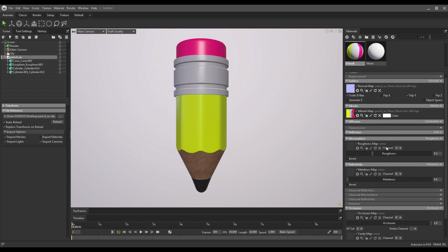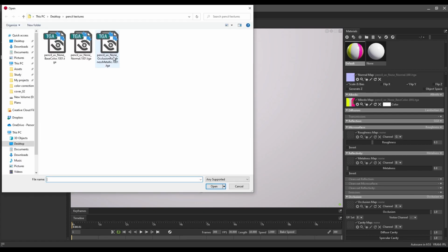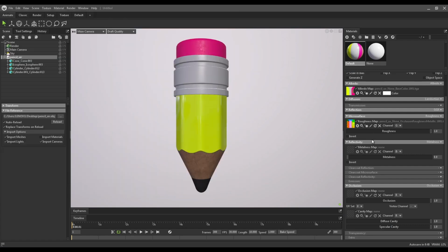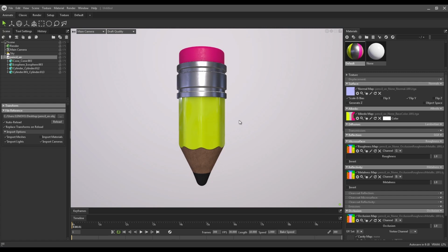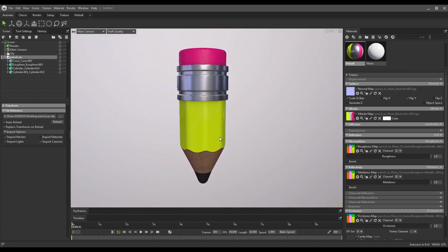All right, another thing, we have to add the roughness. Right click, copy textures, and right click, paste texture. Also paste texture on the occlusion. The point is your normal should turn off this sRGB color space. Your albedo has to be turned on, and also these three have to be turned off. This is a tip. Okay, we just added our textures.